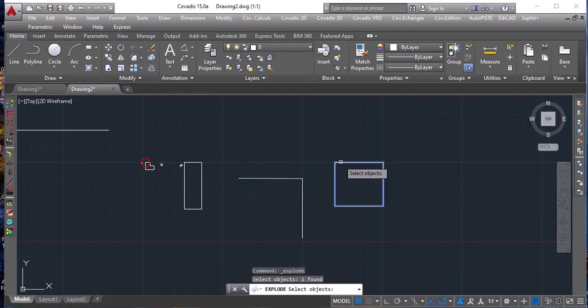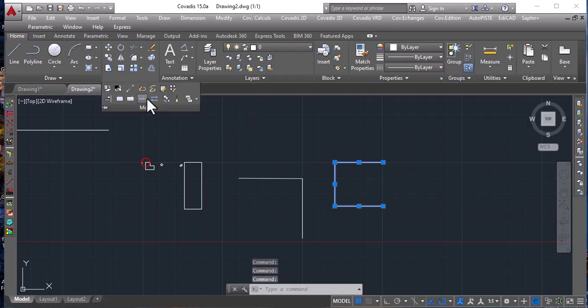Now you have all the different elements, and you can decide to delete a particular element. So imagine you had a drawing and I want to create an opening. Rather than starting back, you can just explode. You create it, you delete one, and then if you like to continue with the other one as a polygon, come back, and this is your result.